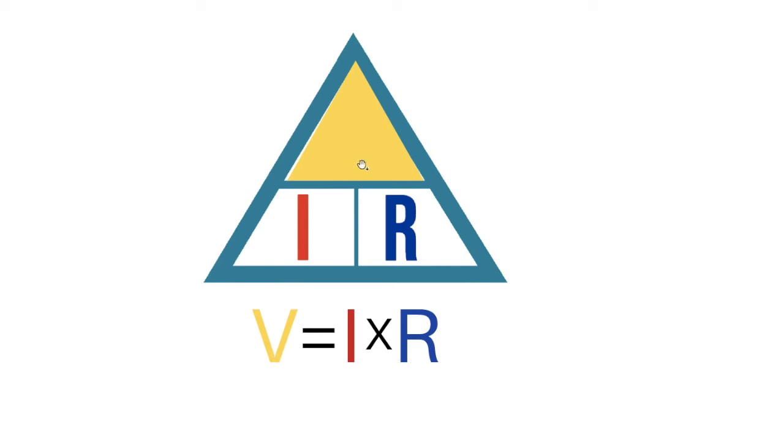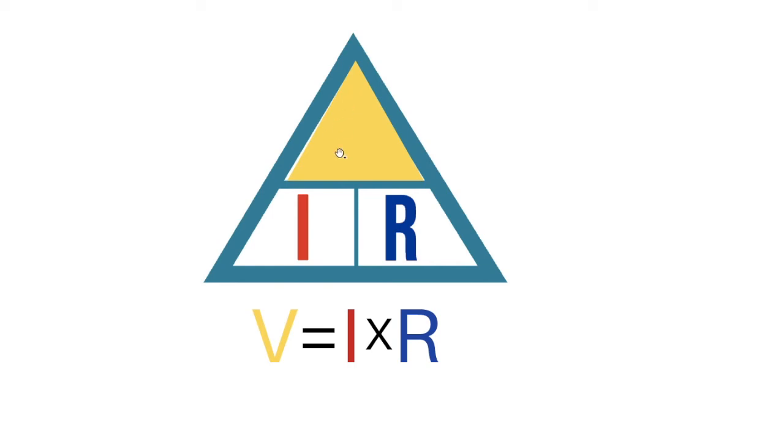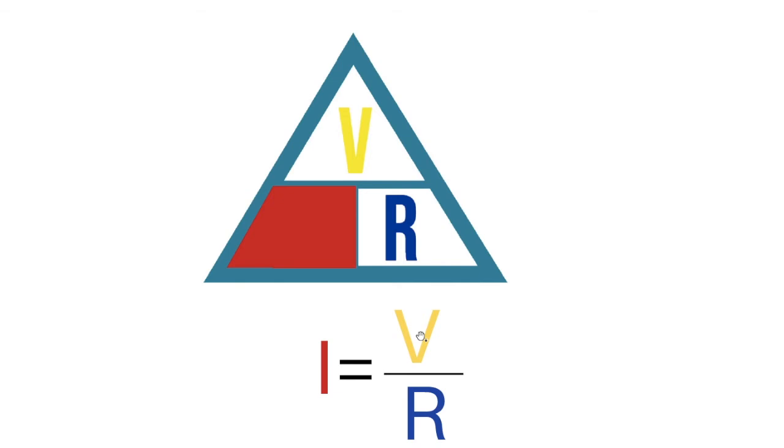If you require voltage, remember voltage is on top, we just close this down and we say I multiplied by R, we get voltage, right? Amperes multiplied by ohms will give you voltage. Now, if we want current, we simply close off the current tab, and then we have V divided by R. You can see this is almost like a division sign.